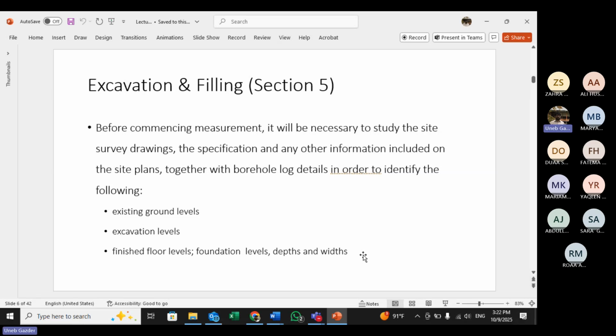Borehole is very common in Bahrain as well as other countries. In Pakistan, we use it even for getting to the groundwater level as well. So they use it in houses as well. But anyway, it's a big drill machine, not a small one, which you use to extract a soil sample from some depth. So it's not like you are taking it from the top. You are going maybe 1 meter, 2 meters deep and then extracting the soil sample.